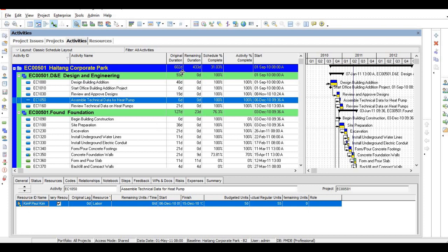Suppose you are giving 602 days, and they say you have to complete the project within 400 days. In that case, they will ask us to create a new schedule. Based on their requirement, we have to reduce the duration. You have to find out which activities can have their duration reduced and arrive at 400 days.